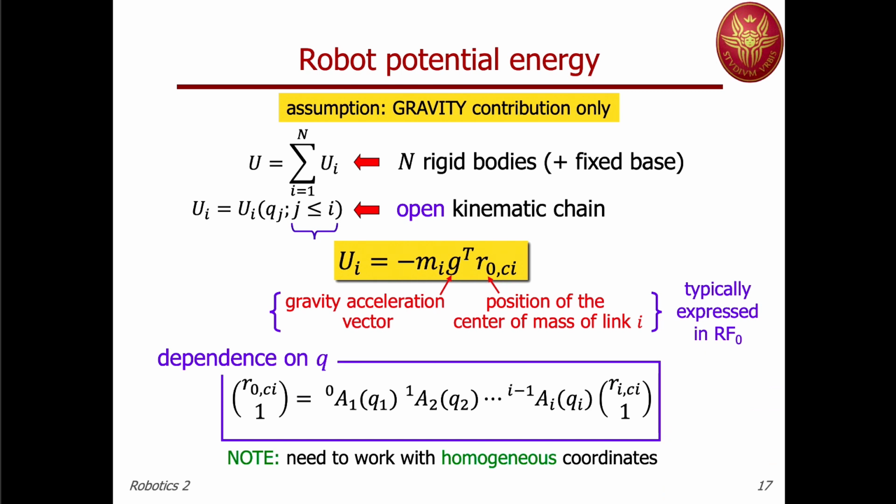we know that we can compute this vector starting from the vector, these are applied position vectors, that goes from the origin of frame i to the center of mass of link i, and the frame i is attached to link i, so this vector is constant and can be defined once and for all for any rigid body. Again, I'm using my pointer.